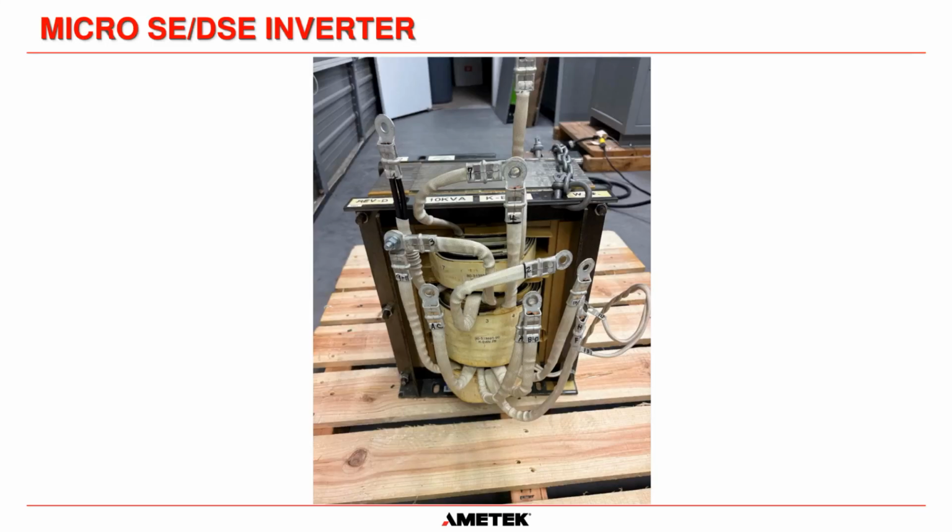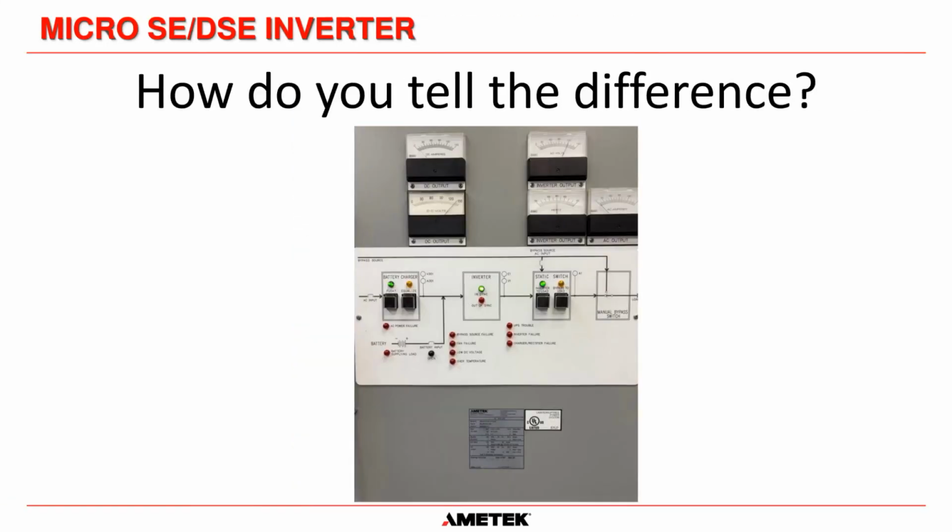But the important thing to remember is you can have varying voltage going into the primary of a constant voltage transformer, and the output remains constant at a certain value. For a 120 volt system, it's going to stay around about 120 volts for varying inputs.